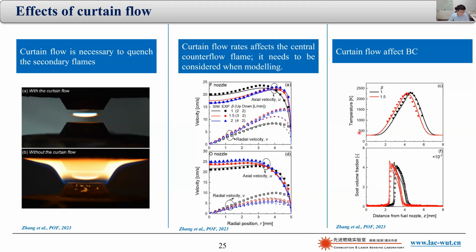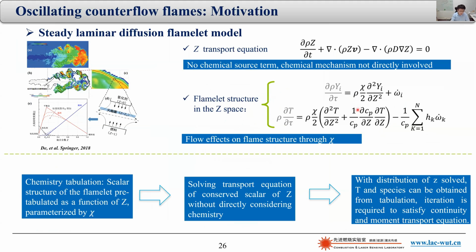Okay. So finally, I would like to describe some of our recent work on measurements in oscillating flames. The motivation of doing oscillating flames really has to do with these two temporal terms in the laminar equations. For the static laminar models, these two terms are generally neglected. So the laminar equation can be solved separately without considering the flow field. So the results can be tabulated, which is a very efficient model to use.